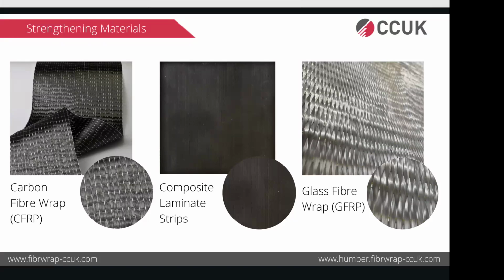But as you can see, because it's an already cured material, you don't have too much flexibility to work with it, because you cannot bend it on site. You cannot go according to the shape of the structure if there is an awkward shape and all. For that reason, the fabric system is quite commonly used around the world. The plate has its own uses.